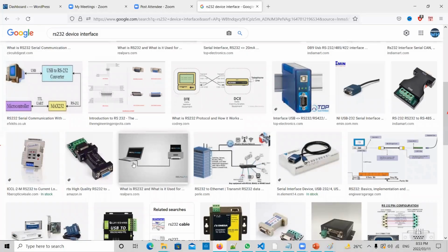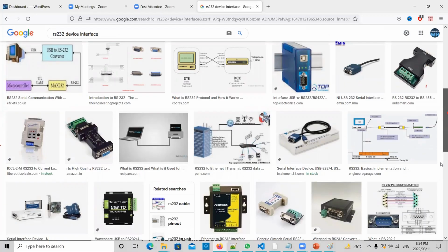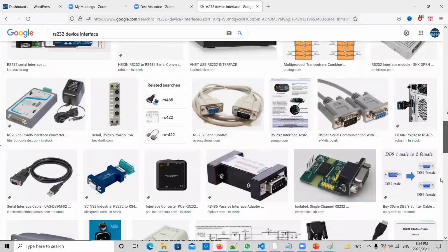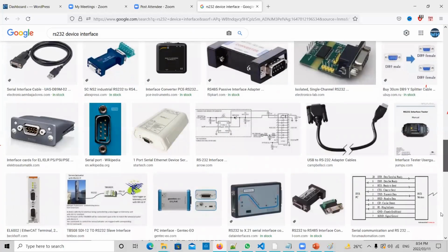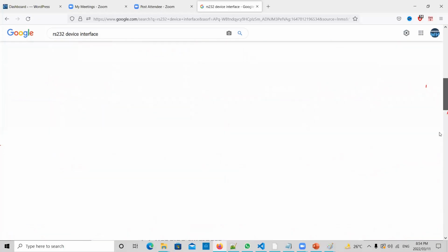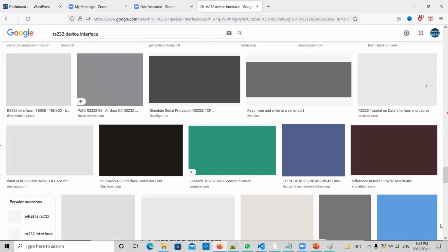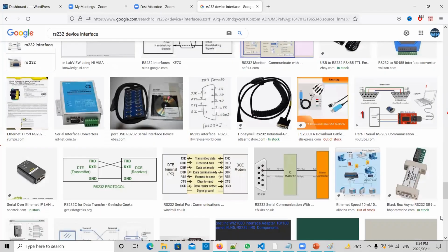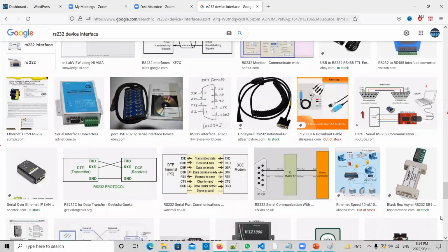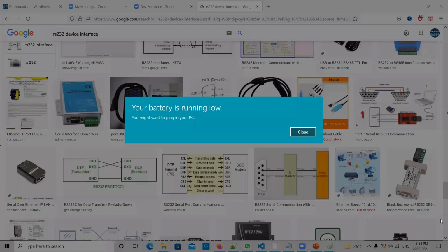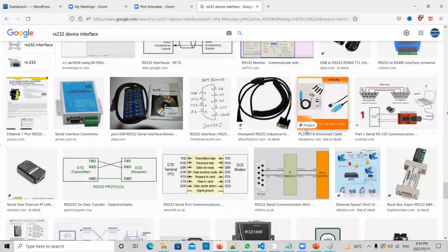The printer is connected with the laptop using USB, which is nothing but a serial communication only. The same as RS-232, but the speed is a little bit higher, that's all. They are using the USB standard. Programmable power supplies are interfaced with the PC via RS-232 communication. The flashing devices are also interfaced with the PC via RS-232 communication.